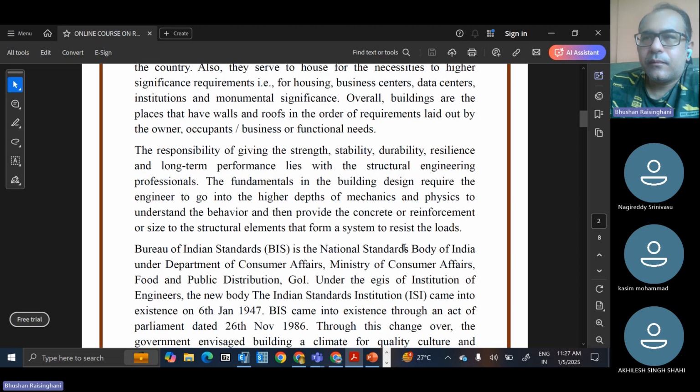So that is very critical: what type of assumptions you are making and which beams you are releasing. If you are able to control the flow of forces just by detailing, you need to justify that, which many people are not able to do. I have seen buildings in which the majority of beams are released.